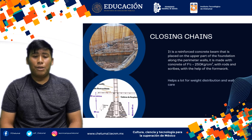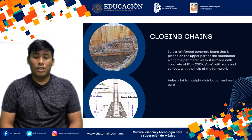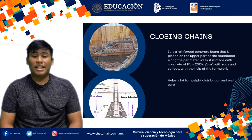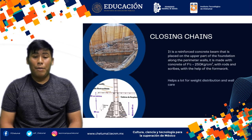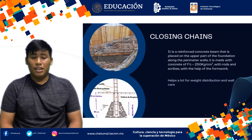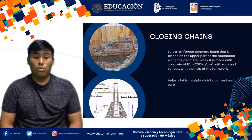Images of a foundation beam under construction, showing its connection to the foundation and the reinforced columns. We begin with foundation beams. These are horizontal elements of reinforced concrete placed over the foundation and extending along load-bearing walls. Their main function is to distribute the loads of the wall to the foundation uniformly and connect the vertical reinforced columns, providing rigidity and stability. 2. Construction. They are assembled with steel reinforcement and filled with concrete. Proper execution is essential to avoid deformations or failures in the walls.